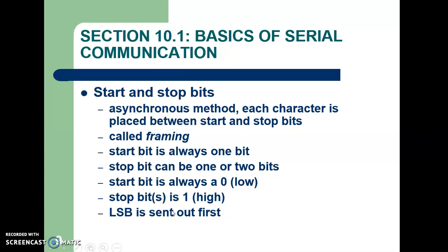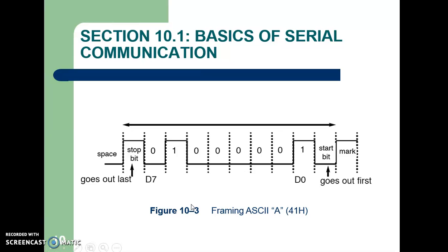These are the rules of the UART protocol, the Universal Asynchronous Receiver Transmitter protocol. These are the fixed rules, and both receiver and transmitter should work according to them. Then only can we send or receive data efficiently. So this is the framing.